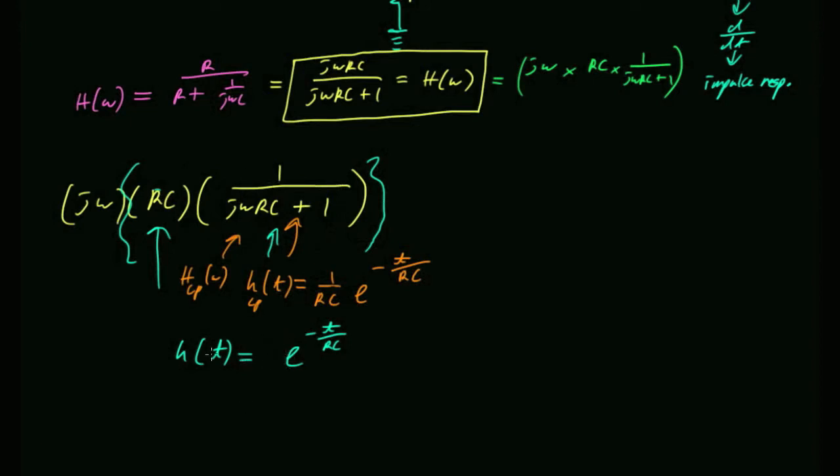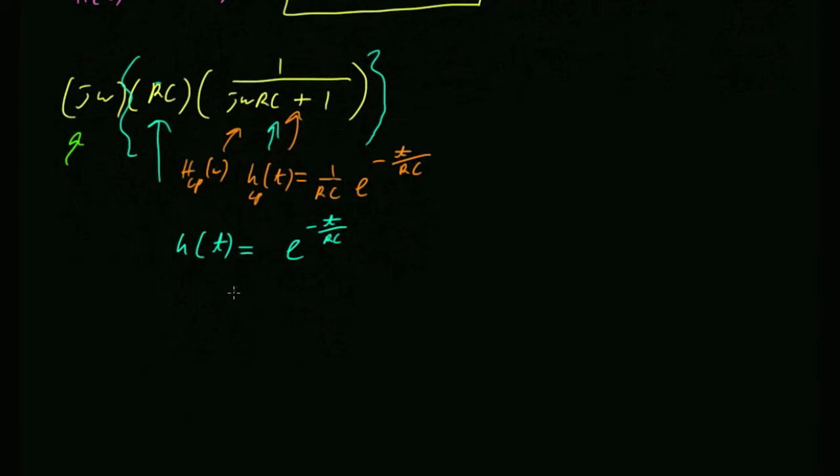But I still have to figure out what the effect is of multiplying by j omega. That's differentiation. So will we integrate that? No. So do we just differentiate? Yeah. We've learned this. If you take a Fourier transform and multiply it by j omega, what is the equivalent operation in the time domain? Differentiation. So if I take the derivative of that expression, what I'll be left with is the impulse response of the high-pass filter. Isn't that cool?